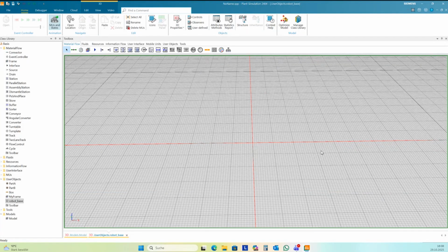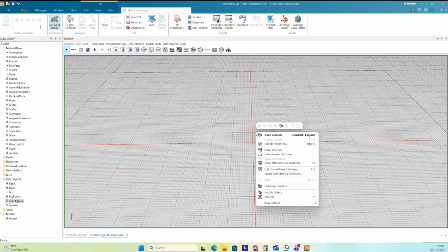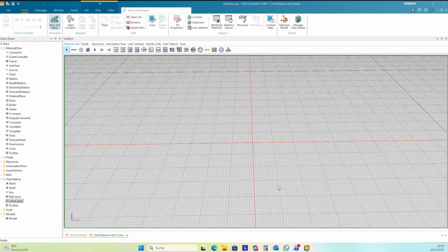In the zip file, you can find three S3D files. I know you know the difference between JT and S3D. JT is only the graphics, and S3D files are special for Plant Simulation. It also contains paths and joints. I also prepared the base with the right positions of the MU animation points. Okay, so you can exchange graphics.